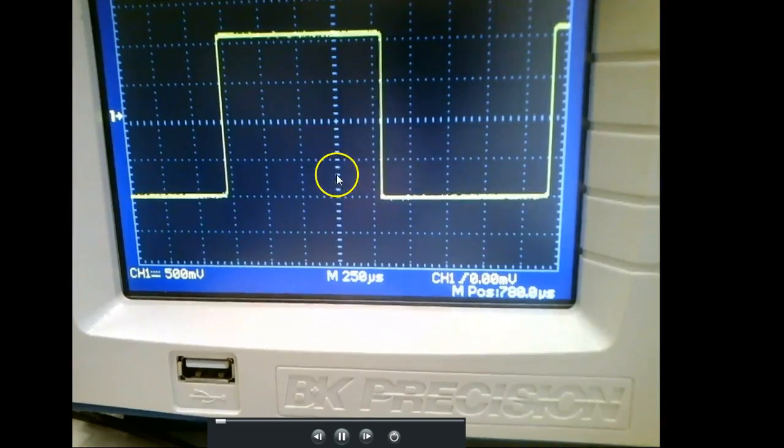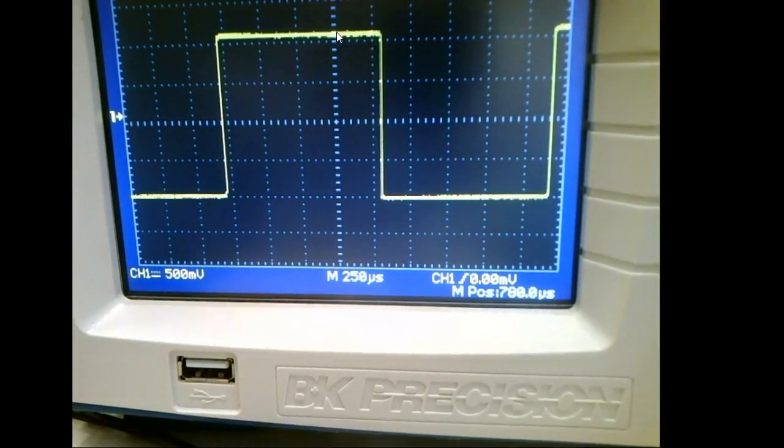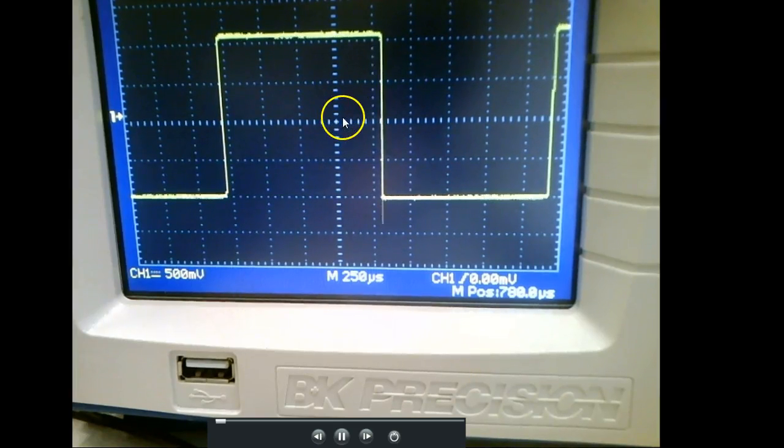So here I would say 500, 1,000, right? Understand? And then I know if it's 500 millivolts per division, each minor division has to be worth 100 millivolts. So I would have come up with it right off the bat. So 2.1 volts. Mr. Reed, I know you asked about that little dash. These are minor divisions. They're 100 millivolts.